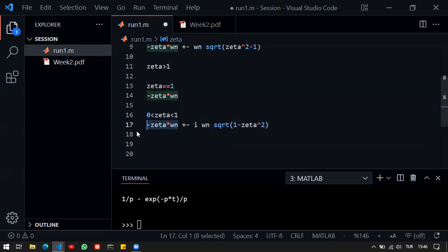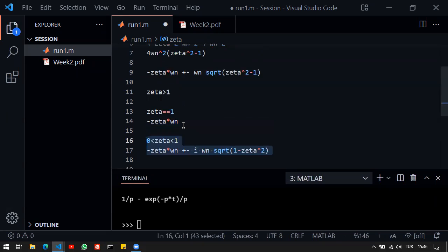And then we would have the real part here. Now, this is basically the solution that we will be mostly working on because we have complex conjugates. If you want to have certain overshoot, then you have to have this solution here. If you want to have zero overshoot solutions, then you would pick zeta bigger than 1 or a zeta exactly equal to 1.